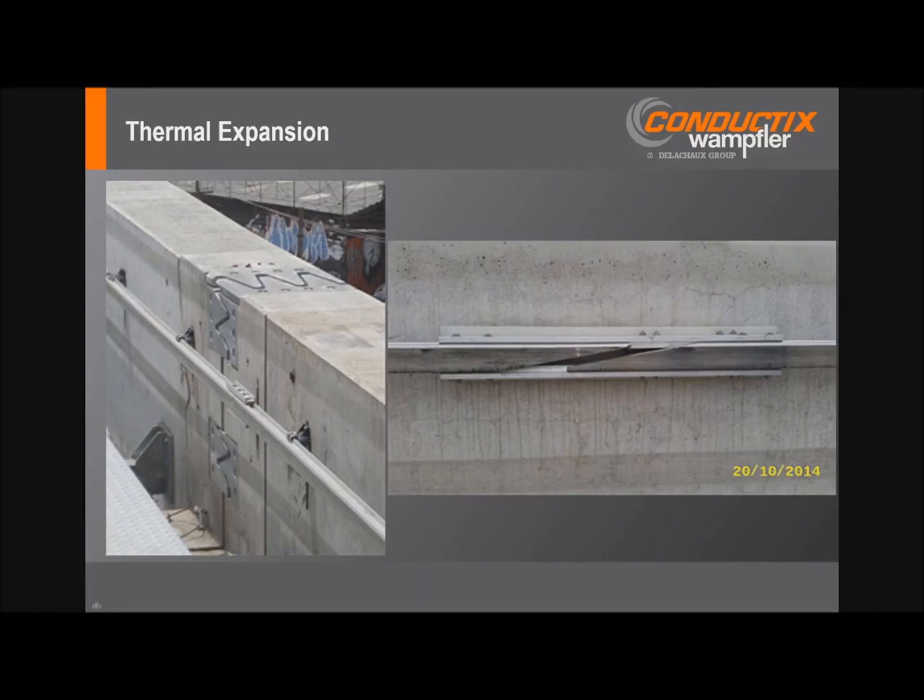Now sometimes, many times, that guideway expansion detail, quantity, stroke, and location is not available at the time of the power rail system quotation. And this can lead to either an unreliable system, inadequate expansion management, or a bill of material and system price changes later in the project. So where possible, it's best to coordinate this as early as possible with the guideway expansion joints. This greatly simplifies the interaction between the two elements and ensures a safe, reliable power rail system.